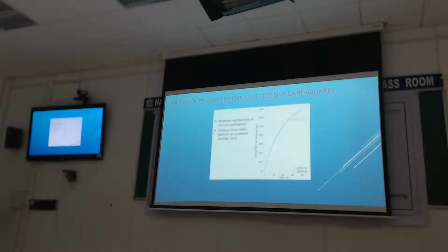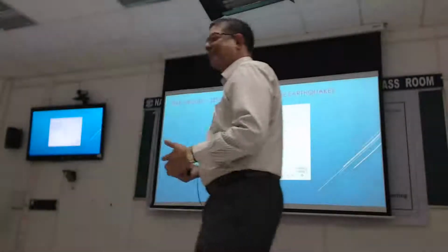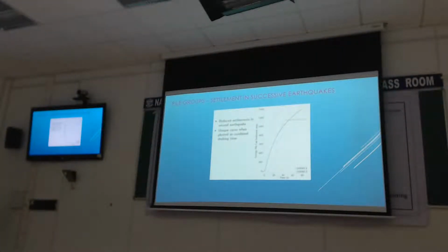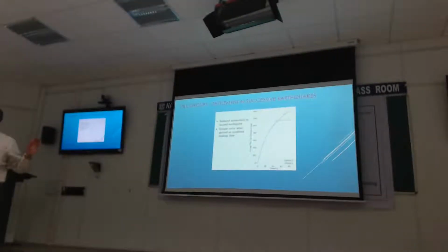Okay. So if I plot my second earthquake, not starting at zero, but where this one ended, isn't it remarkable that the soil remembered exactly what it was doing in the first earthquake and continued exactly along the same route? If I didn't tell you that these are two separate events, superpose them together, it's almost like it remembered. The last earthquake happened some 10 days ago. I remember what stress state I got into, and now this new earthquake came, therefore I must respond with this stiffness. And if ever you needed proof that this method of applying multiple earthquakes means that you're continuing the same stress state and no big damage has been done, this graph proves it. So it's very, very critical from a research validity point of view. And it's genuinely surprising how well they fit.